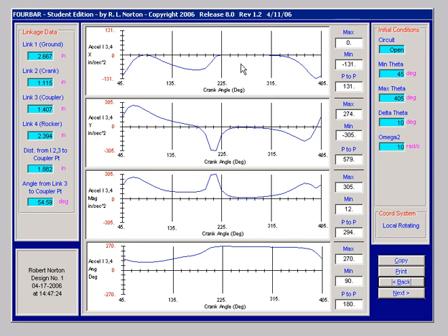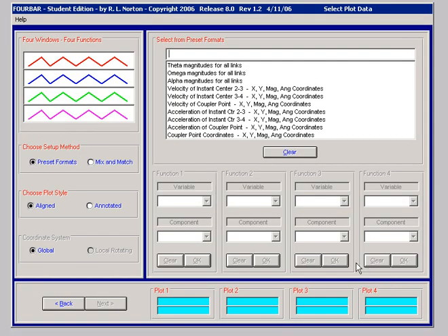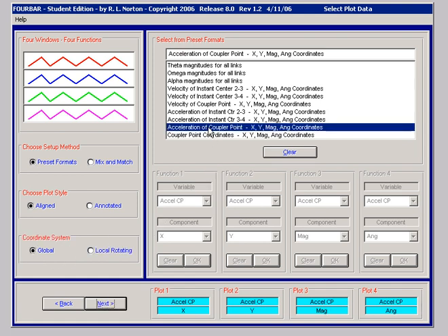So this coordinate system is painted on link 4 in essence and is rotating with it. Its origin is located at I34. So I can take my choice of coordinate system if I have chosen an item for which it makes sense. So I could do the same for the coupler point.